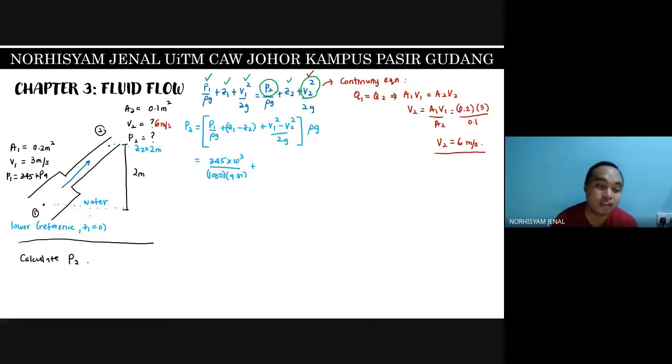Okay, but in case point 1 over here, we know the elevation from the ground is 1 meter, for example, and point 2 is 3 meters, then you can just use the numbers 1 and 3. But for this study, we don't have the elevation from point 1 to the ground, we only have the difference in elevation. So because number 1 is lower, we designate it as a reference, so Z1 is equal to 0.